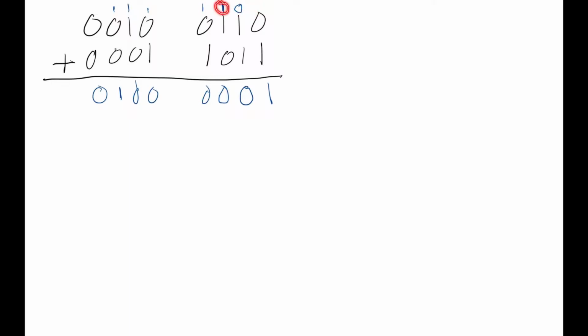So this one is the carry in from that bit. Now our circuit is also going to produce two outputs. I only showed you a circuit that produced one output before, but don't worry, two outputs is easy. It's just really two problems in one. So our circuit's going to take these three things in as input, then it's going to produce the answer as an output and also the carry out.